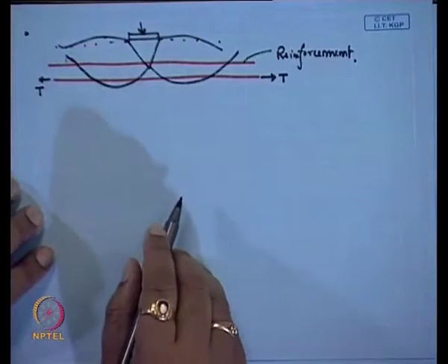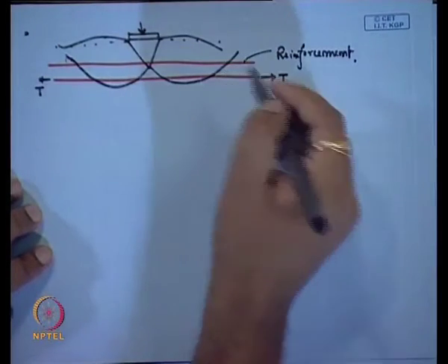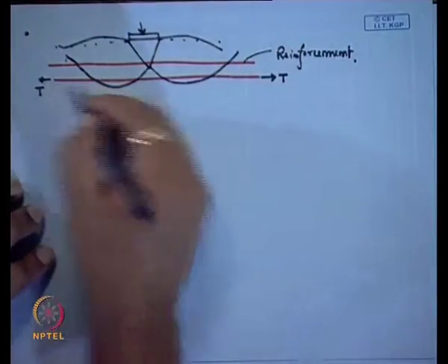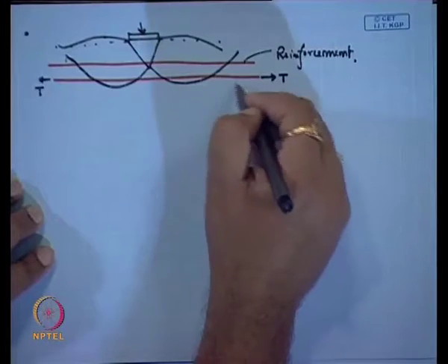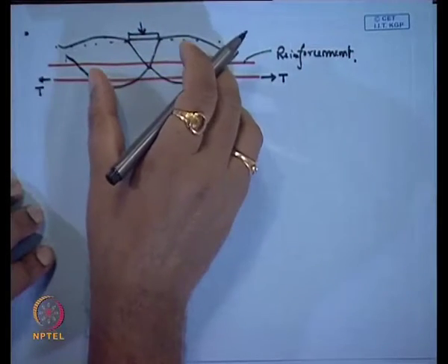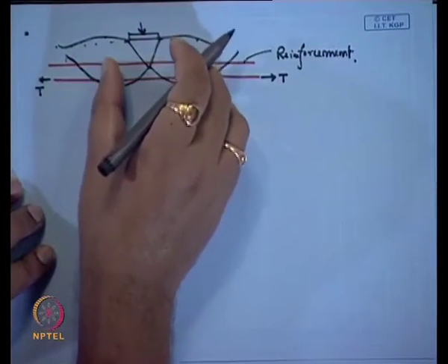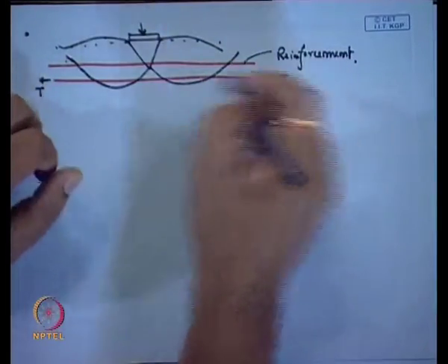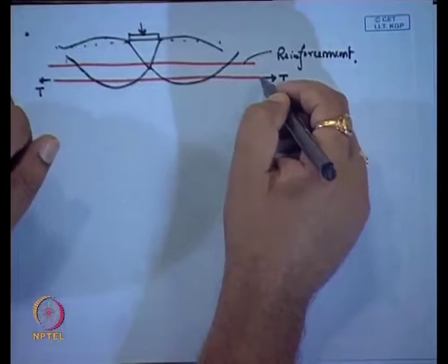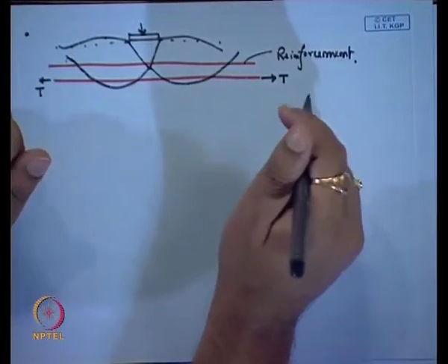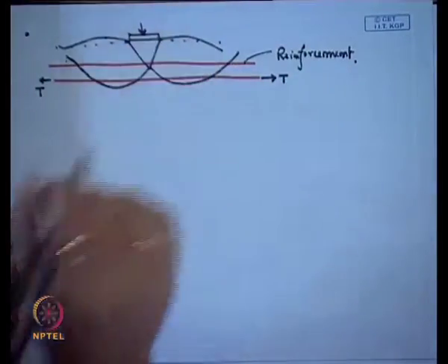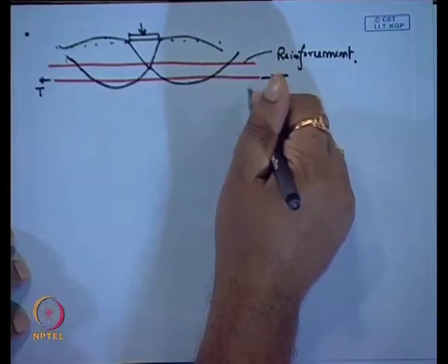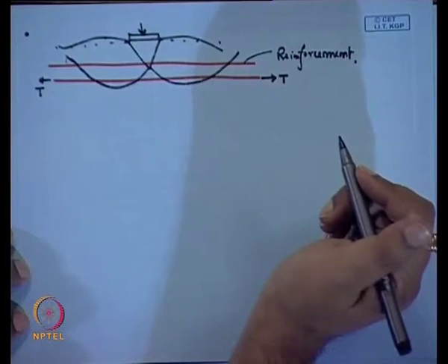Why is this tension developed? We can say that it is because sufficient anchorage is there. That means the soil is holding this reinforcement, and the reinforcement within the center region is moving downwards. If we hold something on both sides, suppose we are holding this reinforcement on both sides, and the soil is moving in the downward direction, one tension is developed within the reinforcement.